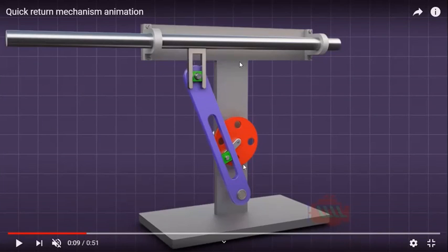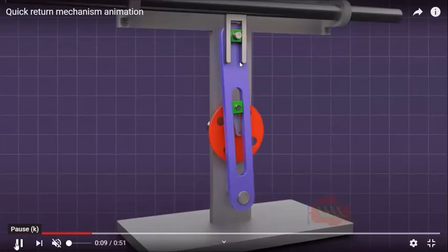Okay. So in this lever, when your wheel is rotating, because of this slot, this link will act as a rocker. So it will go till some place and then again it will come back. And because of this rocker mechanism, this part which is attached with the end of the rocker will move in linear direction. But obviously you have to give some guideways over here, otherwise it can also oscillate, which you don't want. So just to make that motion linear, you give the hinge over here, and also some supports or guideways. Okay. So let's see how it will work.